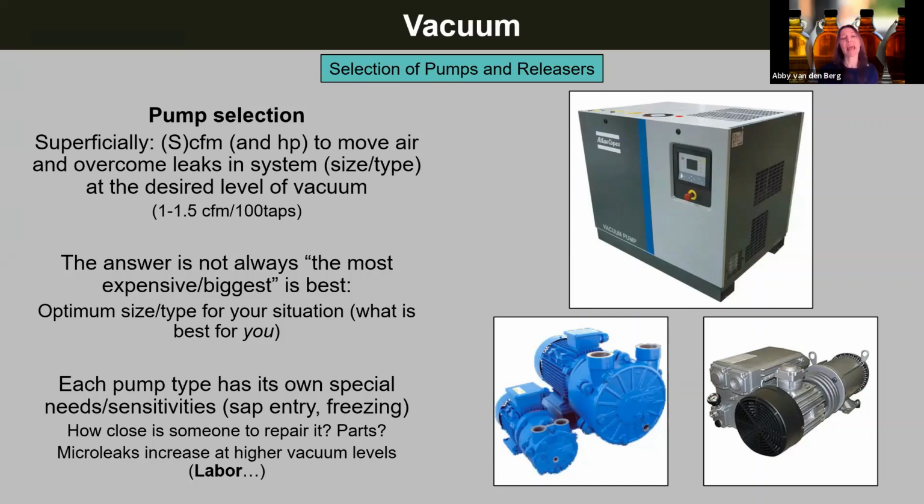And then other questions that are also super important is, how close is someone to repair this pump? Am I going to have to wait a week for someone to come from 3 states away to repair this pump if it goes down in the middle of the season? Do I need to have 2 spare pumps to compensate for it because of that? How hard is it to get parts for this pump? How much maintenance? Those are all questions that to me are very important when selecting a pump.